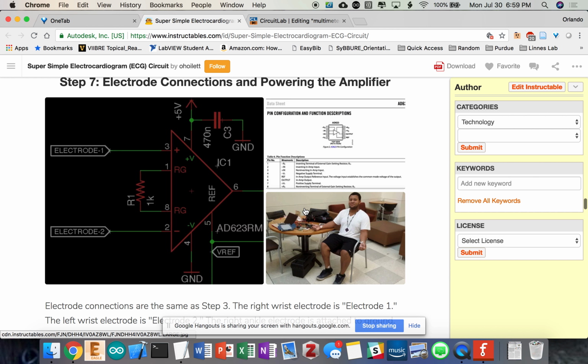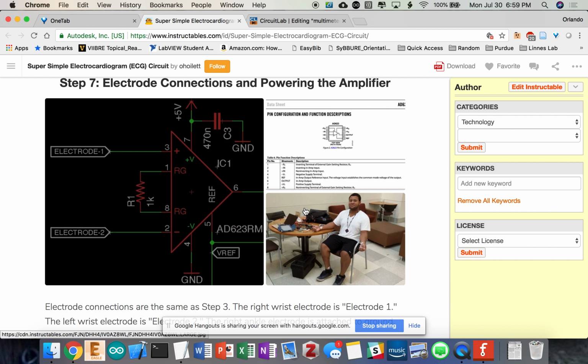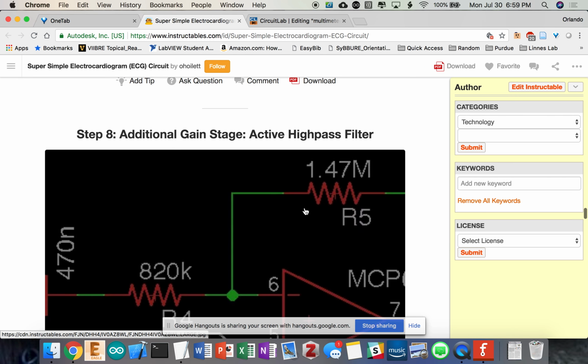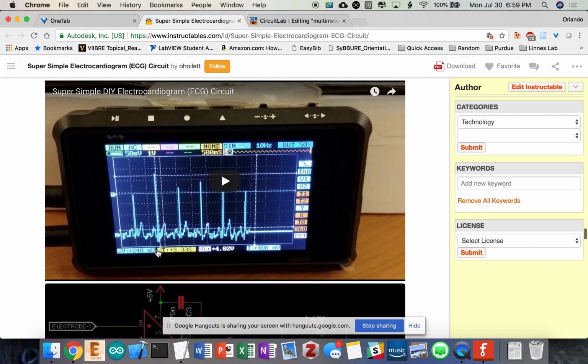So in your photo, when you have the electrodes on your wrist reading your heart signals, are you also reading your nerve signals as well? The nerve signals for my muscles? Yes. I could be. Whenever you get this ECG signal, and you actually start flexing, you'll see the EMG signal, electromyography, which is the nerves that innervate your muscles, bleeding into your ECG signal. In this setup, it's configured ideally for ECG, but if I flex my muscles, I'll start to see components of the EMG.